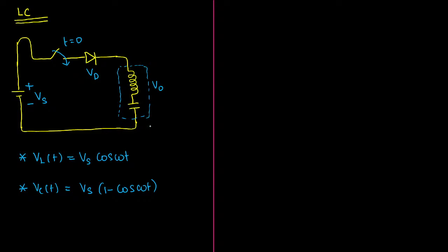Sir, I wrote the expression for the voltage drop across the inductor. I wrote the expression for the voltage drop across the capacitor. Supply voltage is written. Something is missing. What is missing? Current flow through the inductor, or through the capacitor, or current coming out of the supply. Since all are connected in series, they all will be the same. Most important repeated question. Here, this value will be simply supply voltage into square root of C by L into sine of omega t.